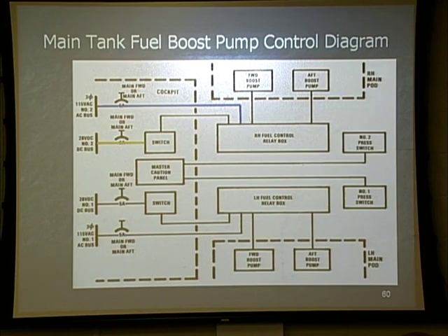Why? DC control that stuff, right? Exactly. All that this is helping us do is reinforce the fact of what? If we lose the DC switch or we lose the DC power, we're still going to lose the pump. That's all that this is reconfirming. Fair enough? So they go to the switch, to the relay box, and now it's going to go to those pumps and activate it. What's actually going to the pumps? AC power. Any questions about that?